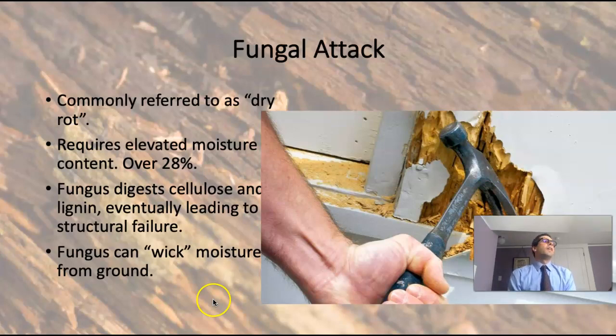So it's something to look out for, and kind of the telltale signs are the paint starts to look a little weird. You can look at the side of it, and you'll see that something's happening below the paint surface. It's not flat looking, it looks soft. And as soon as you can start pushing into the wood, you know that you've got a problem, and usually you just kind of need to remove that stuff.